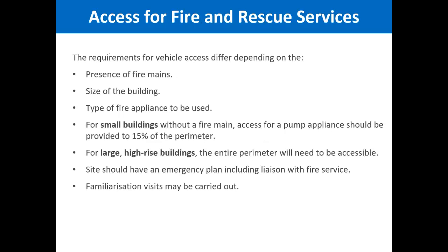This is very, very important. Most of the time, you must have seen outside various buildings, there is a dry riser or a wet riser. That basically is the point where the fire pump comes and it can connect its pipe, and the whole piping system is available inside, and you can extinguish the fire using that as well.